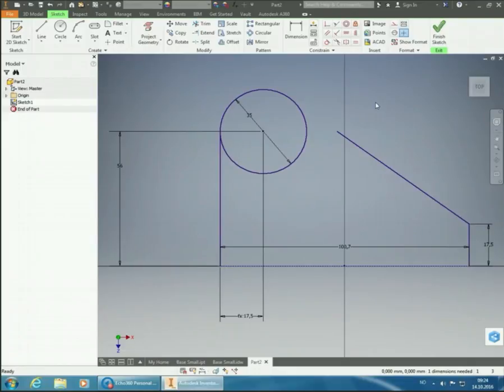That's not a problem. The next thing we need to do is to use the coincident constraint, where we connect one point to another. So this one, the coincident one. We select that one, and we do the end of our line, and then we click on our circle. So then it gets completely stuck to our circle.